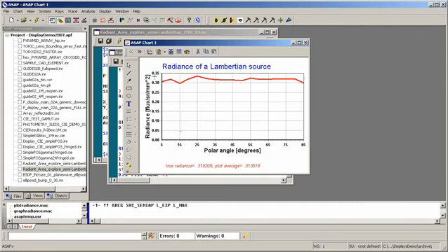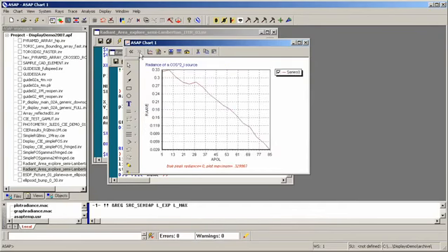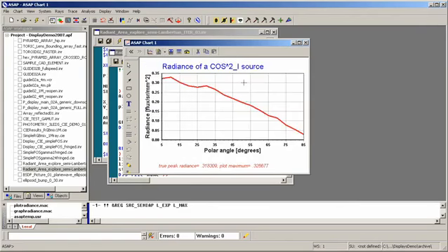And we see a radiance function plotted by the horizontal viewing angle, and this is from the normal, and we're actually starting at about 5 degrees and going out to about 85. And we see that the Lambertian source produces a flat radiance function. So we're Lambertian in the horizontal direction, and we see a flat radiance characteristic in that direction, exactly as we'd expect. In the vertical direction, and again, let me use a plot template to make this a little bit nicer.